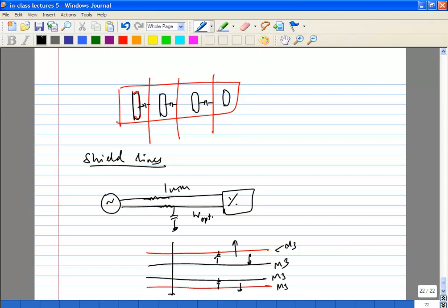Second thing, you can, for example, use it on as far away a metal layer as possible. Okay, so if this is on M3, you either want to do it on M6 or on M1, depending on the signal. So you may not be able to do it on an immediately adjacent metal layer. We'll add extra cap.